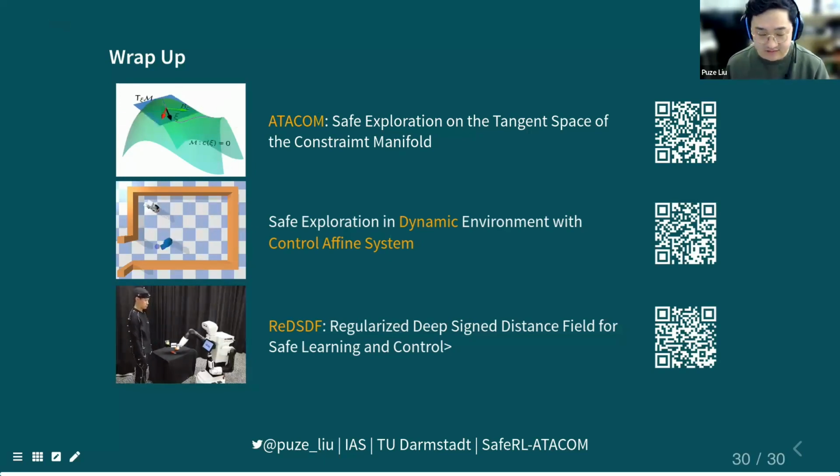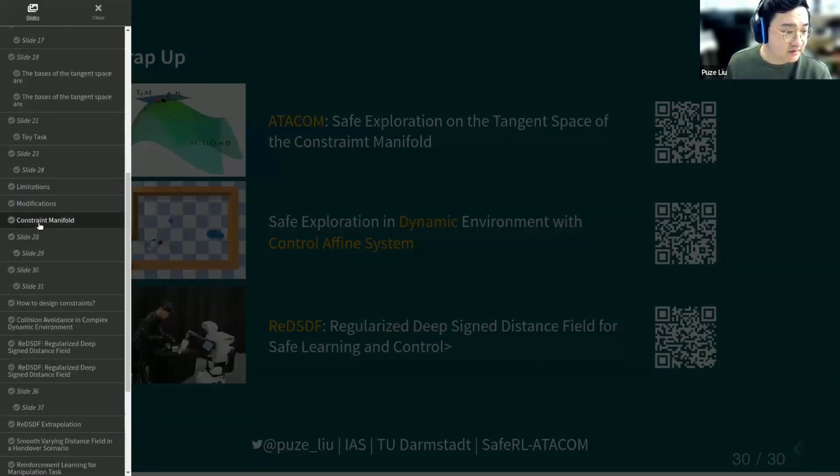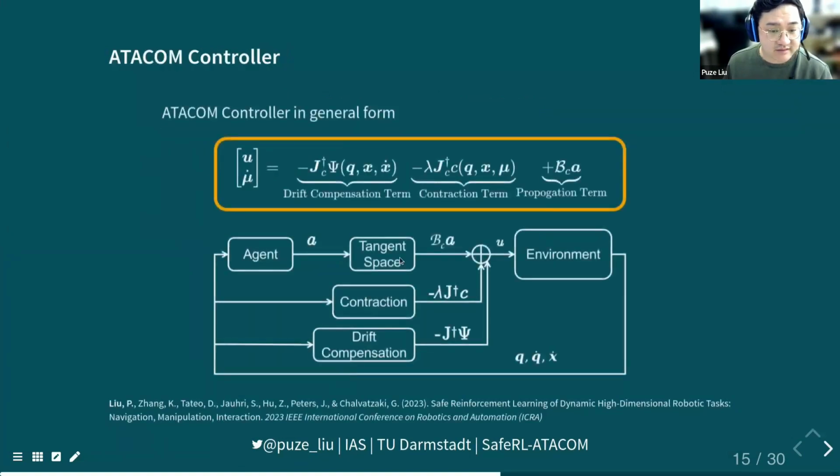Yes, so we actually really need to observe the state. If you see from the controlling paradigm, we need to observe not only the state but also the velocity. In this case, you can assume that the velocity is this one. You can use filtering or some state estimation, like a Kalman filter, to estimate it, or you can also assume that this goes to 0. It's actually also working well in practice, but theoretically there will be some issues.